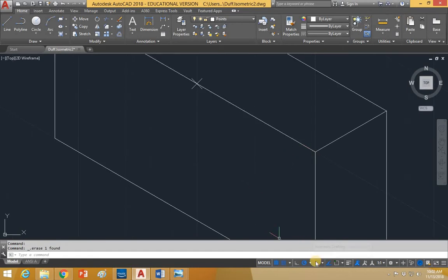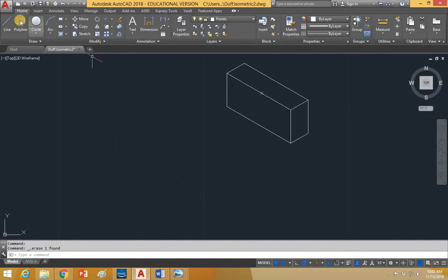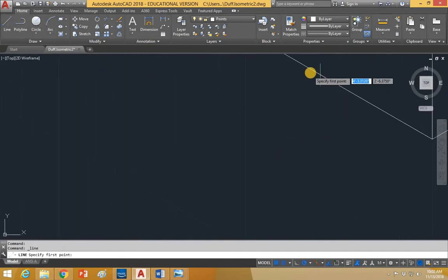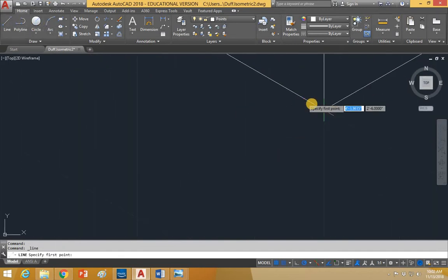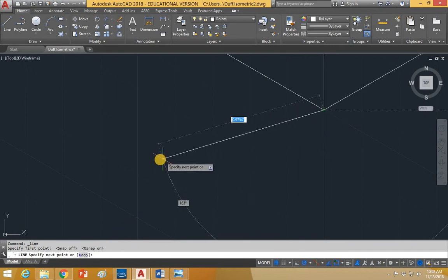And I typically want O-snap on because there's so many times that it's helpful. So like when I draw a line, if I want to draw another line and I want it to snap to one of these intersections, see, I have O-snap off, so it's not doing that. It is snapping there because my grid is, so I'm going to turn my grid off too. How about that? So see how it won't snap to that? So if I come down here and I turn O-snap on, now it will. Which can be helpful because if you're trying to connect two lines end to end, it's helpful.